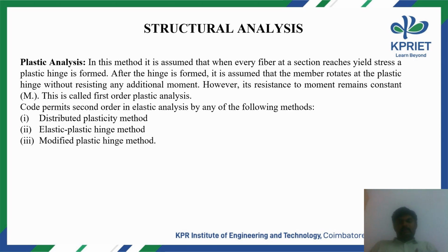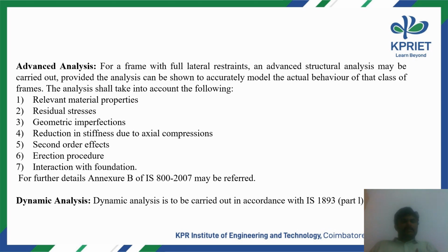Another name for plastic analysis is yield analysis. Advanced analysis is for frames with full lateral restraints. Full lateral restraint means laterally fixed, so in this case advanced analysis is required, provided the analysis can be shown to accurately model the actual behavior of the class of frames.